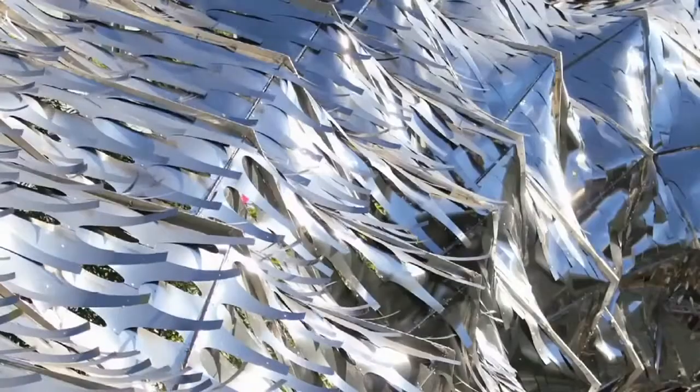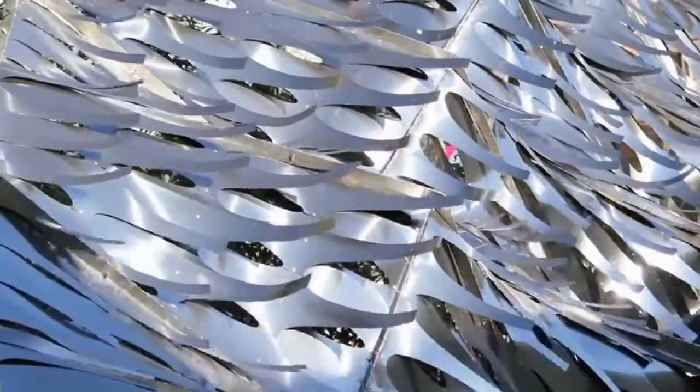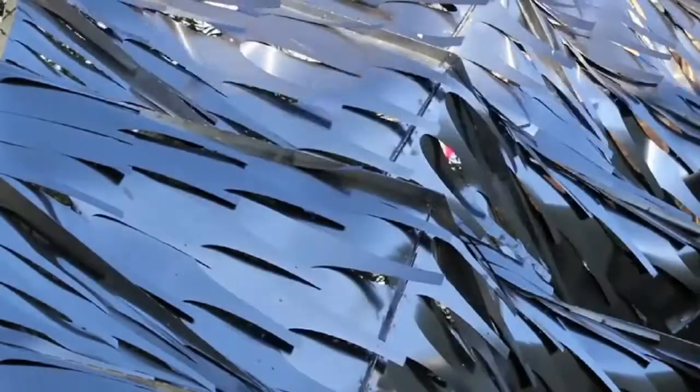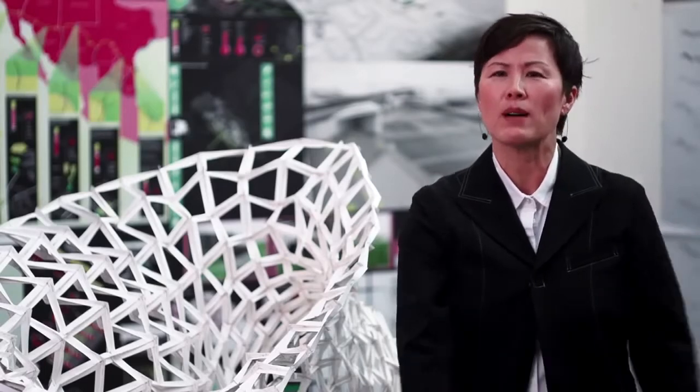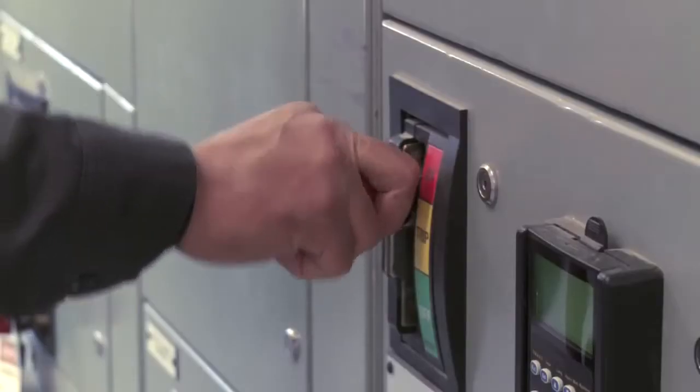But when the sun hits it and heats up that gap in between, the thermal bimetal will curl, and by curling will actually start to shade the area behind it. What it does in effect is it is able to automatically act like a shutter system, so you don't have to open and close manually. So it'll prevent a lot of heat gain from getting into the building and therefore reduce the amount of mechanical system or artificial cooling that would be needed for the building.